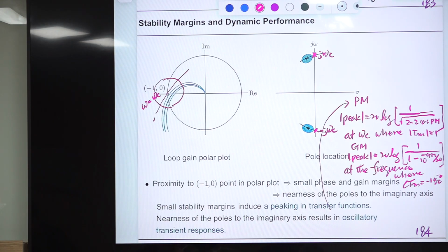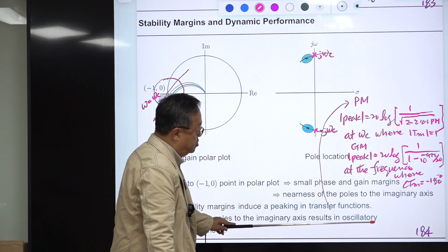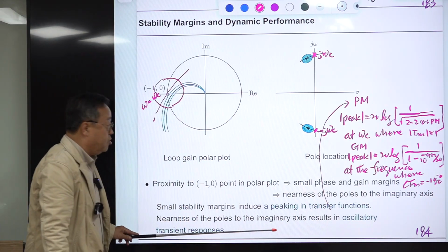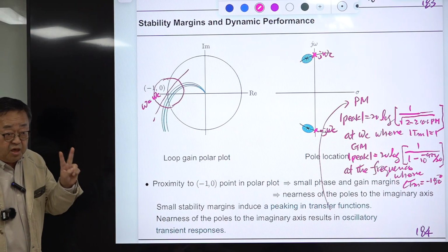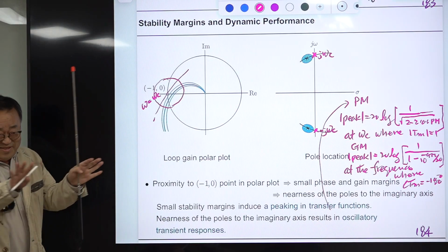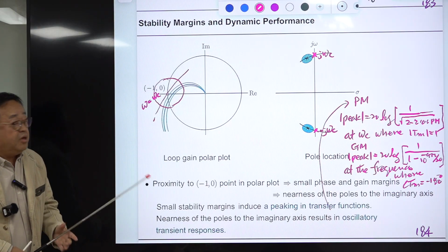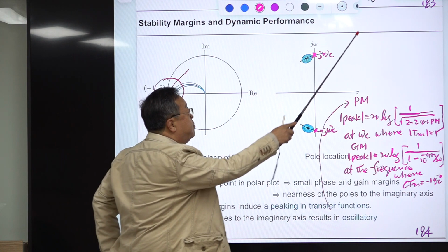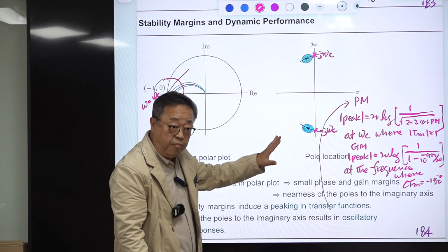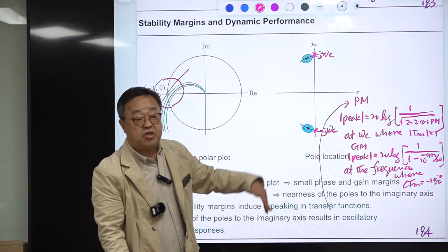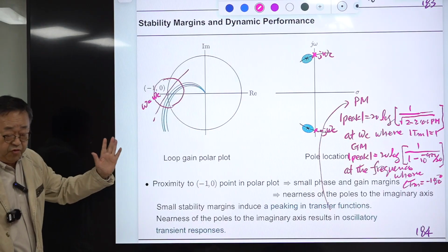This induces oscillatory behavior in the transient response in two different regions, but they have the same origin, though the interpretation can be different. Peaking means there is an undamped second-order term that will produce oscillation at a particular frequency. We already discussed the oscillation frequencies.